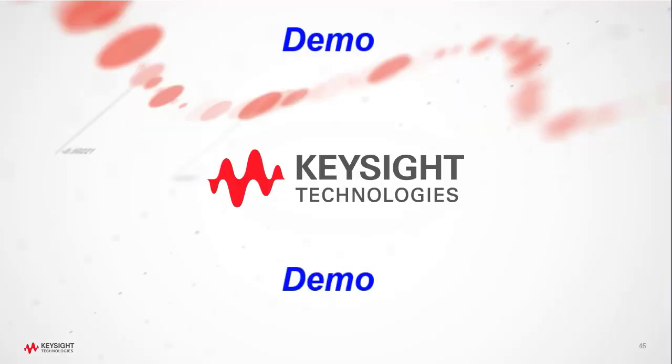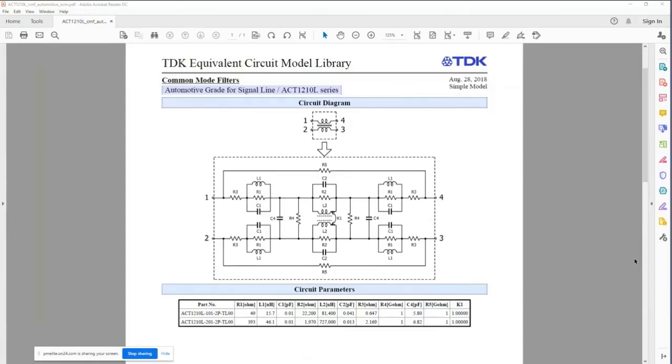All right, so I'm going to switch to a demo here real quick. Okay, good. This library model has been my backdrop, so I wouldn't forget it. This is a common mode filter, a common mode choke, that will be used for common mode noise filtering. This TDK part is pretty popular, and it's a common part. TDK has a nice library of components, and they supply different versions of the models for them. This is a SPICE model, which you could use, or you could use S-parameter measured data that they supply as well.